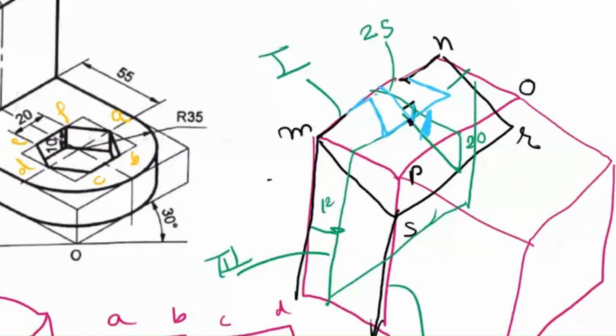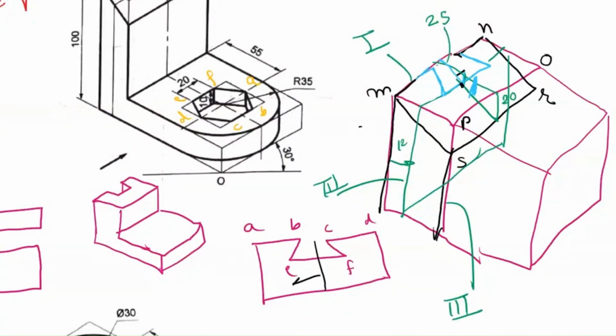तो कैसे ड्रॉ करेंगे? See, take this much distance in compass and cut an arc here. Take this much distance in compass and cut an arc. So this is F and this is E, and join it. That's it. And this is B and this is C. So this is the slot now on inclined surface, and this is the slot on rectangular surface. ये sloping surface पे slot है. Okay, तो प्रोसीजर में इतना ही करना है.